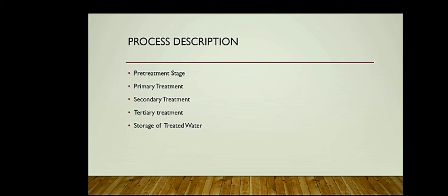First, the raw pre-treatment stage. Raw water is first stored in a cylindrical storage tank in order to settle heavier particles like sand and clay. A separation screen has been provided at the outlet of the storage tank in order to prevent large particles from passing through.